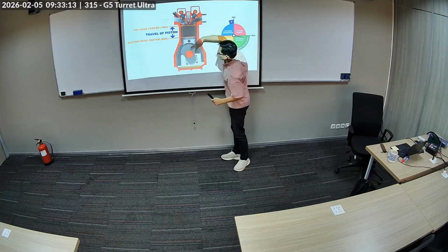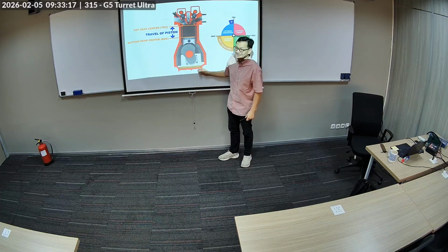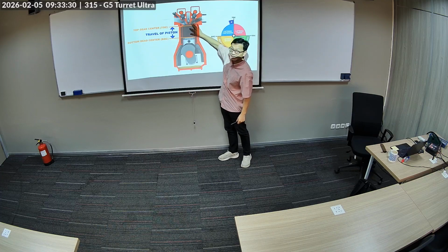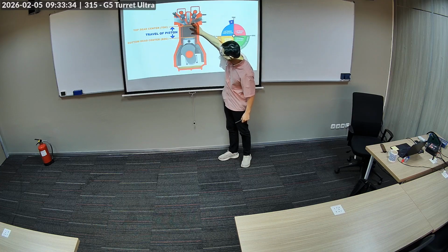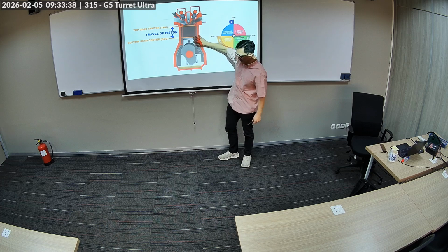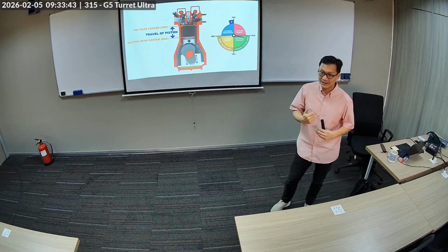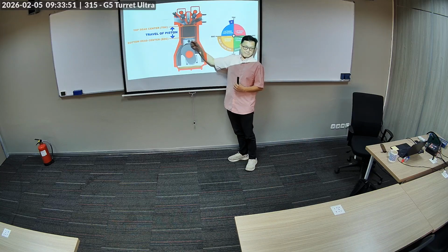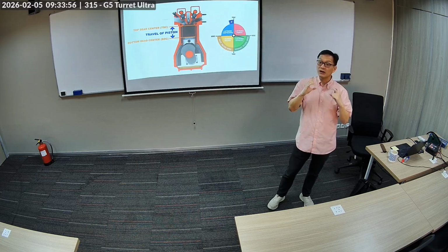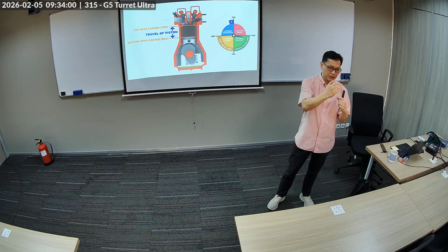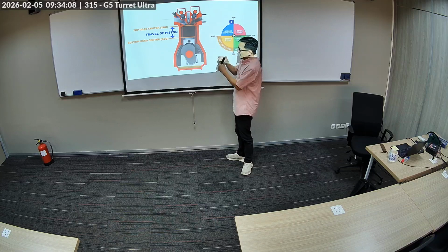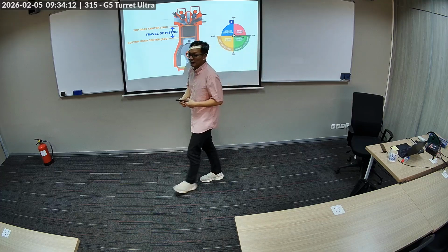What happens when you go very fast? What's gonna fail? Well, this guy, the pin. And this guy is going so fast, and then it has to stop, right? And then it goes fast again, and it stops again. So this guy is actually experiencing a lot of acceleration and deceleration, right? And the faster you go, the more extreme the acceleration and deceleration of this guy. What happens when you make the stroke shorter is that you have comparatively less acceleration and deceleration every time it goes up and down. So by shortening the travel of the piston and making the bore bigger instead, you actually have a higher revving piston. But at one point, I mean,